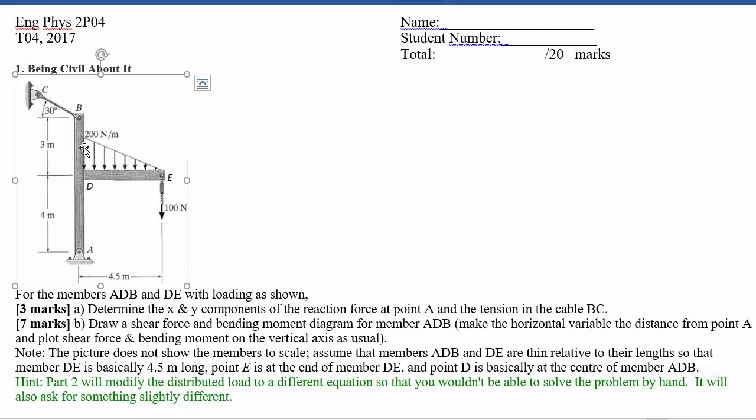And locally, the force is 200 Newton per meter over here. So you'd multiply that by 1 centimeter and get 2 newtons in that 1 centimeter on the left. And then in the middle, it would be 100 because it's a linear function. If you're halfway along, you've gone halfway down towards the other end, which is 0. So we would have 1 Newton in a centimeter across the center part, and then 0 newtons in a centimeter at the end. That's just telling you how you would have a load that's distributed across the top like that.